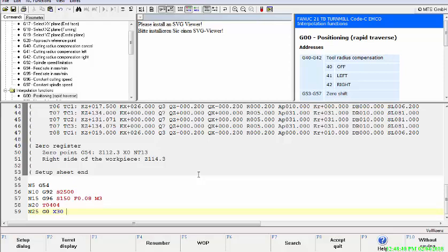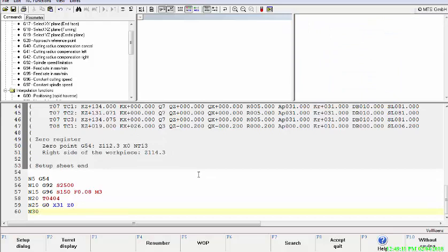And then my Z is 0. Well done, because in my settings I made my Z as a 0 point in Z. So I will put it right over, X31 or 32 or 33, above 30, and then Z over the 0 point, exactly over the 0 point, ready to cut.